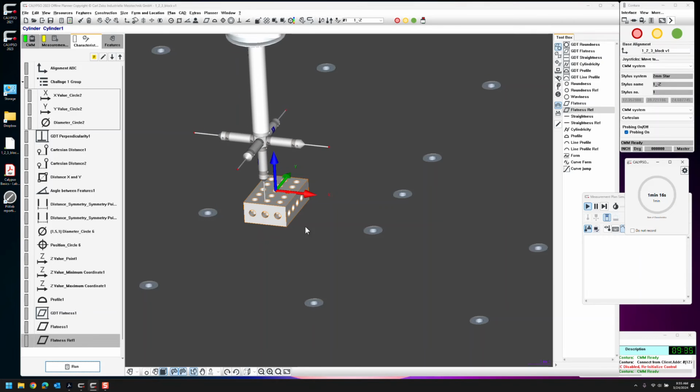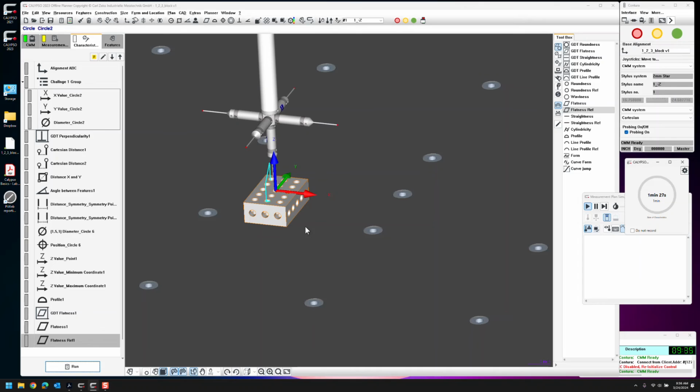And as you increase the speed, when those change by a factor that you care about, typically 1/10 of your tolerance, that's when you've hit the maximum speed you want to go. See, you want to go as fast as you can go before your speed starts to actually alter your result.